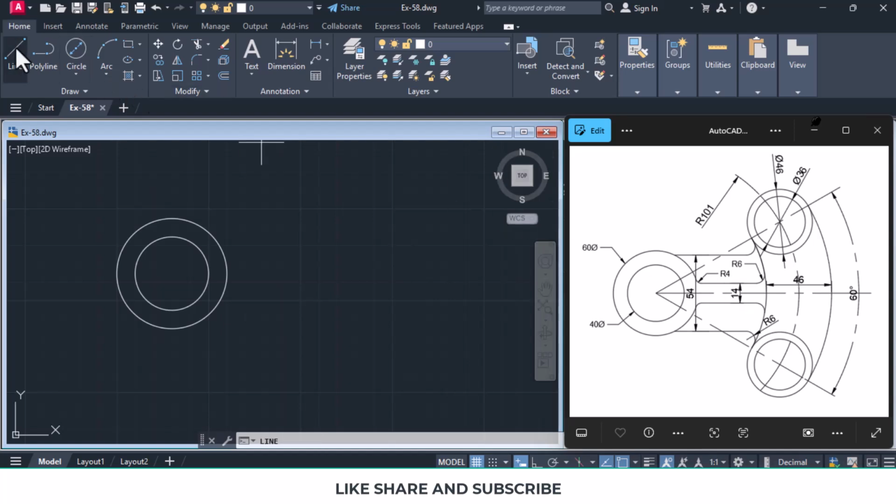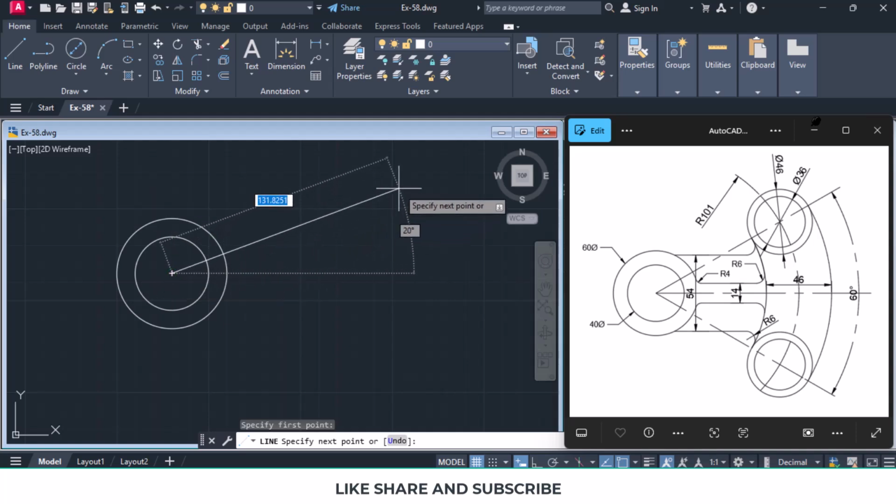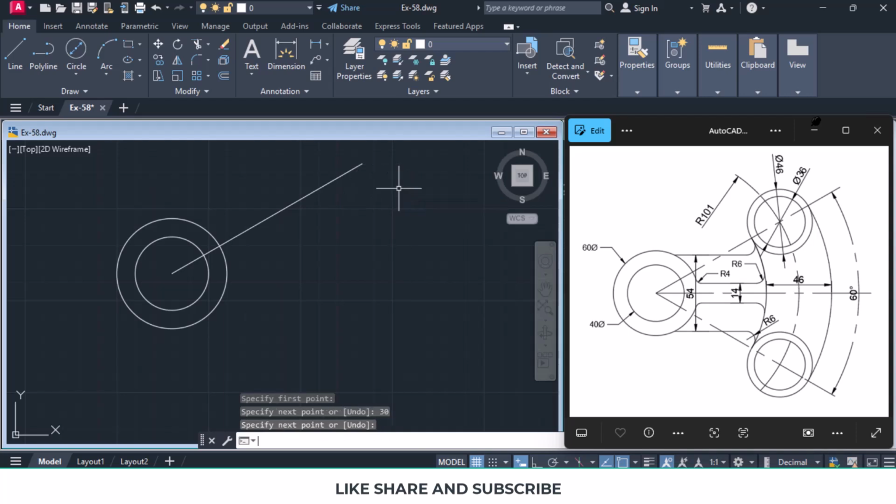So we'll use the line command. It's asking us to specify the first point. We'll snap to the center point of the circle and we'll extend and make the line to something like 120 units. Press tab and we give the angle as 30 degrees and hit Enter. And again Enter to end the line command. So this line can be of any length. In our example, we have given it as 120 and the angle will be 30 units.